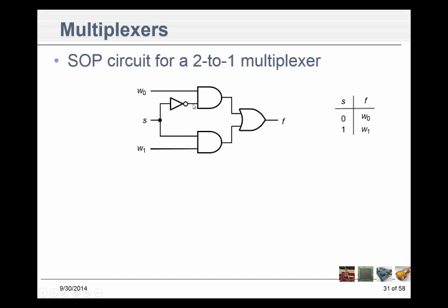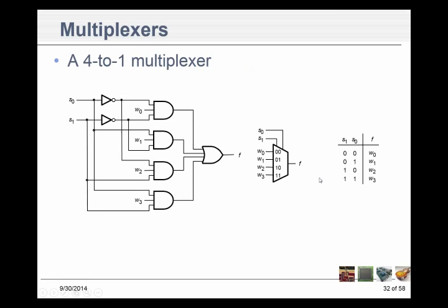Right? Because that makes this a 1 here. So now if this is 1, the 1 gets to the output. If this is a 0, the 0 gets to the output. So this truth table is the multiplexer. They're also called data selectors. They decide which line you're going to choose for the output. Let's see what else we got.